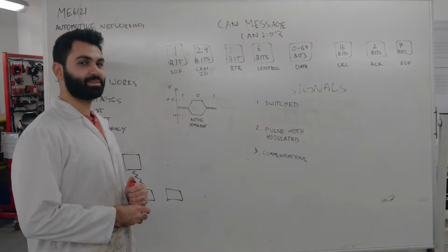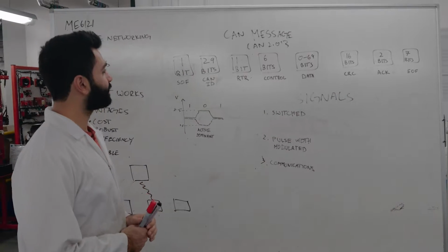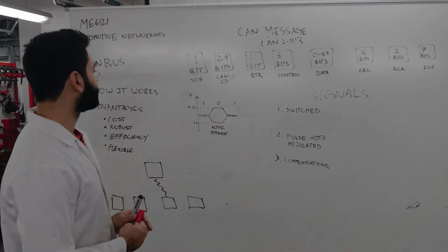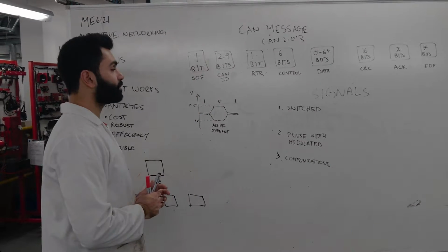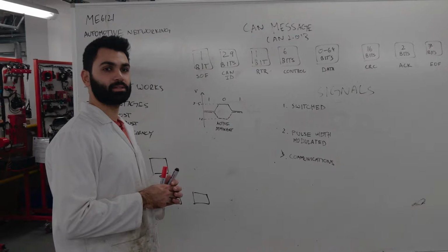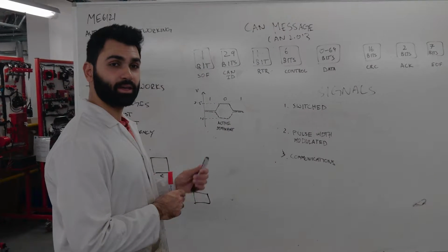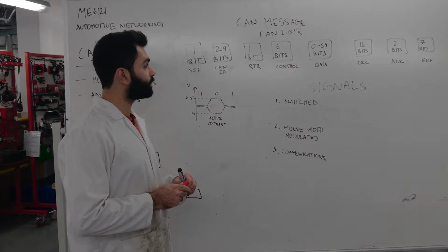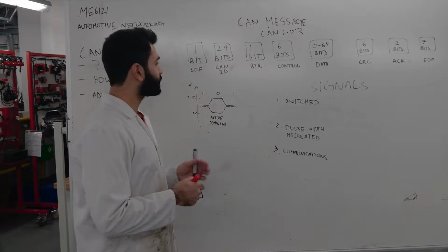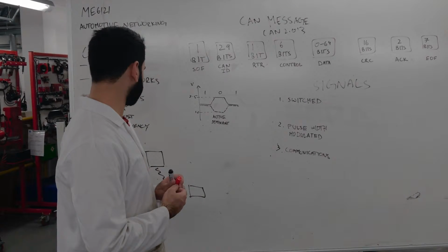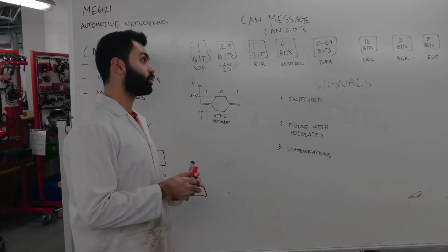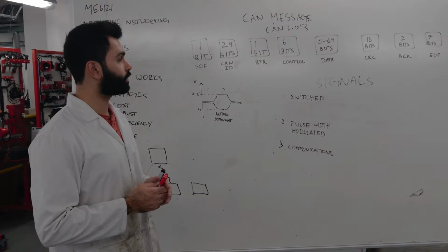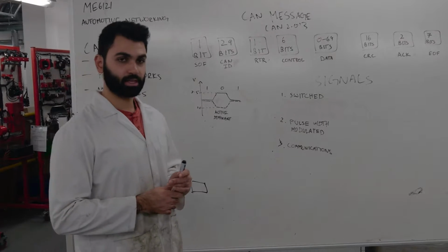So this is a simplified CAN message with extended 29 bits identifier called CAN 2.0B. So we have our start frame, which basically tells other ECUs that the message is coming. Then we have our CAN message identifier, which, like I previously said, prioritizes messages according to number. So something coded 00 would hold priority over something coded 01, for example.